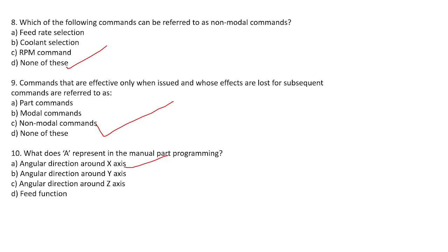That point is set by the machine manufacturer, and it serves as the origin point of all the dimensions and movements in that program. Using the absolute positioning mode, whenever you are programming the part, you can specify exact positions and dimensions for the tool to move, regardless of its previous location.